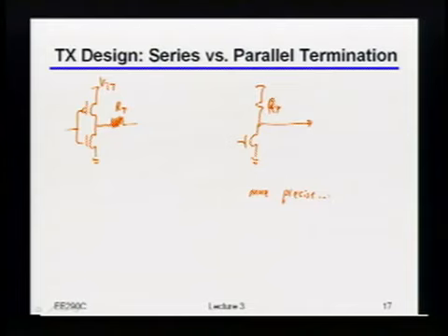Yeah? They are like shunt parasitic capacitances, which will change the... Oh, okay. So it is sort of related to that, but even, let's say, from a DC standpoint. Well, in the series, you kind of still have the devices in the path. But in the parallel, you're seeing the high output impedance. Right. So that's basically what it comes down to. If you want to make it really precisely RT, then you need essentially the resistance of the transistors to be equal to 0.